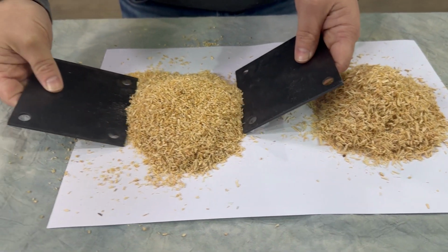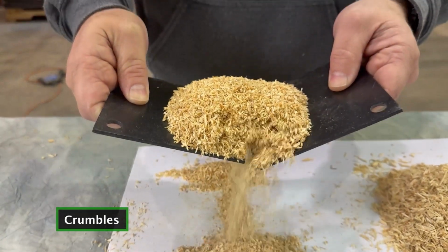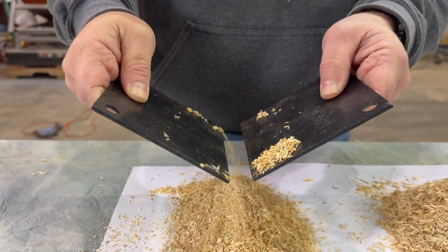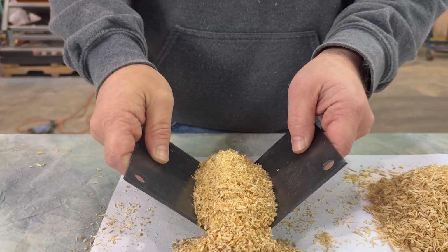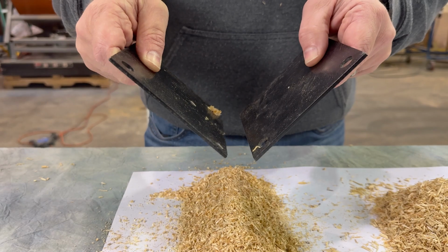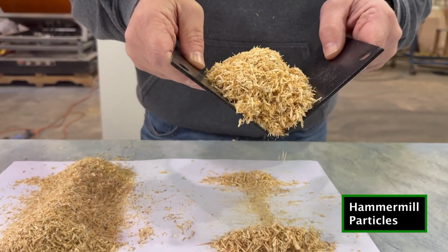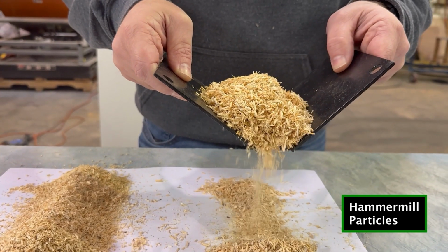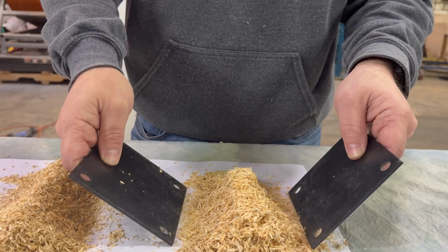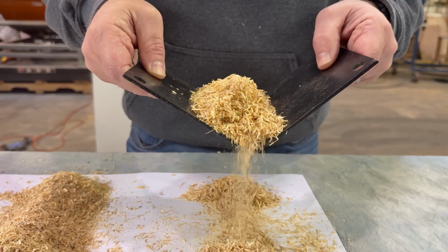So we talked about drying, but now what about material handling? Aspect ratio makes a difference. So if I take my little simulated hopper, I try to open at about the same width. In fact, we'll come up closed, and I open, low aspect ratio material flows quickly. If I go to my higher aspect ratio, trying to keep that similar slope as my initial one, and I open up, you see it bridges or it crosses. I can increase my angle, and I'm still bridging. I have to get a bigger and bigger opening before material flows out.